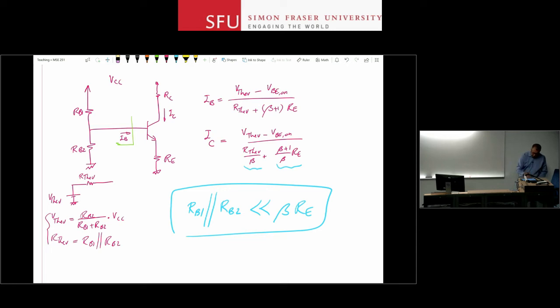Okay. Now, if you look at this circuit for an NPN BJT, it looks like an H. This is your biasing network, right? So RB1, RB2, and RE, the three of them, look like an H. So this is known as H biasing. You use a voltage divider to get the bias voltage that you need at the base, and you use a resistor in the emitter terminal to get the stability that you want for the bias point. This is called H biasing, very popular, and at this point you have solved many problems based on this topology in your assignment and hopefully in practice problems as well.